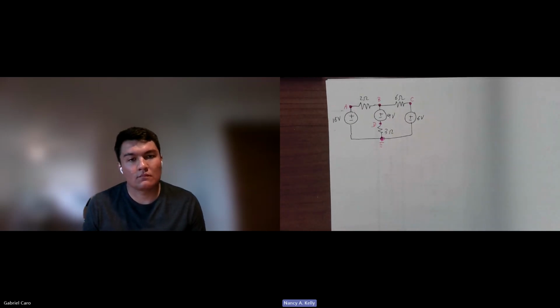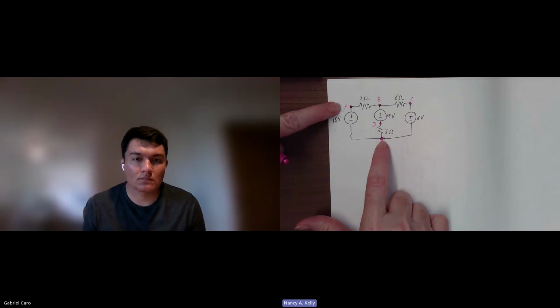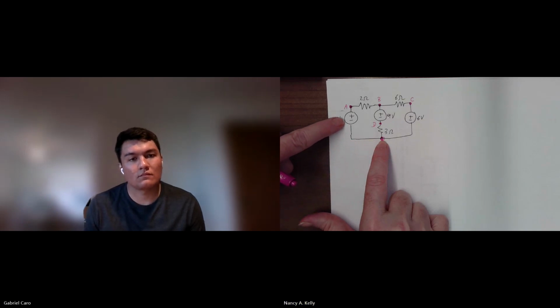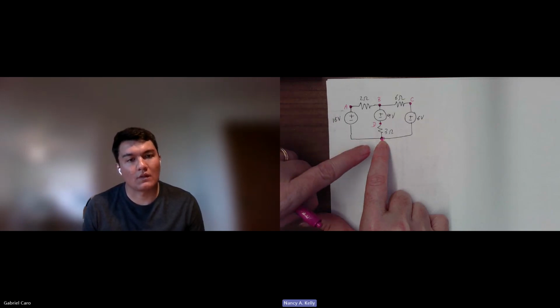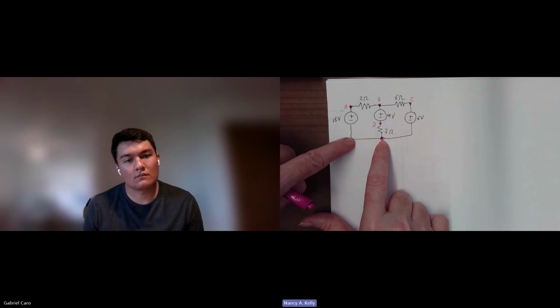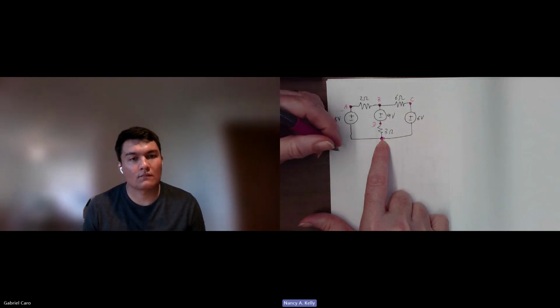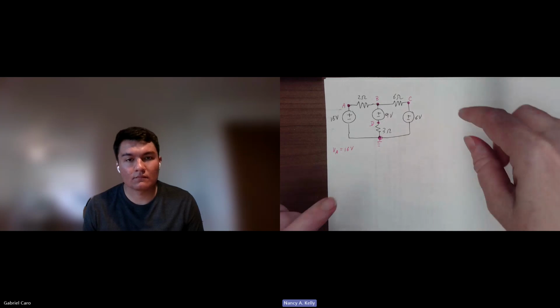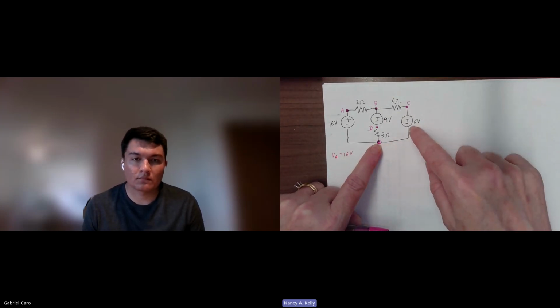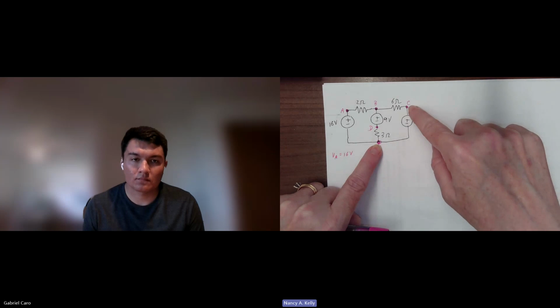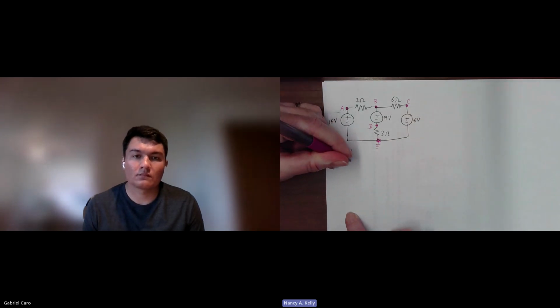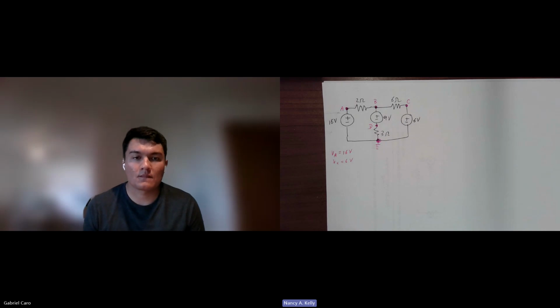Now, remember that the voltage at A is the voltage with respect to ground. So if you look at this, you see it's 16 volts. Because you go along here and you say, that's my reference point, then I rise by 16 volts going through this source. I get to this point and that's A. So the voltage at A is 16 volts. Does that make sense to you? Yes. You can do a similar thing over here, because you also have a voltage source. I'm down here. I rise because of the polarity of the source by 6 volts to get to C. So VC is 6 volts. So I have 2 of these sources already all set.